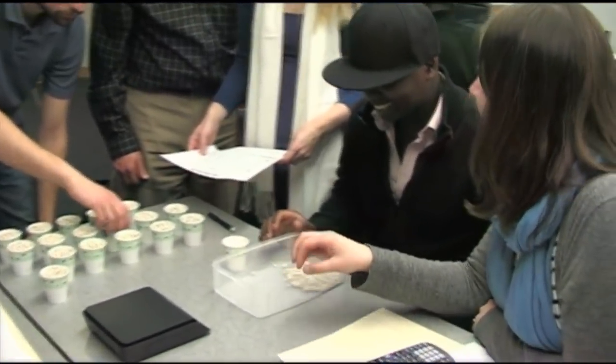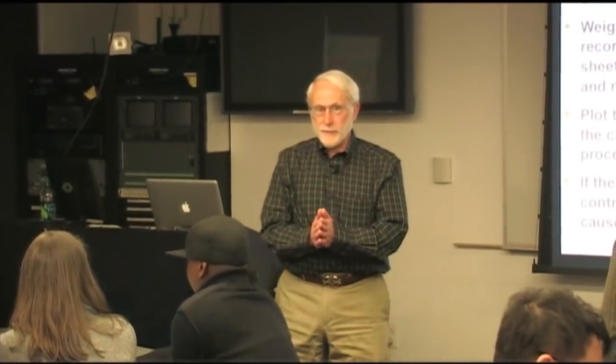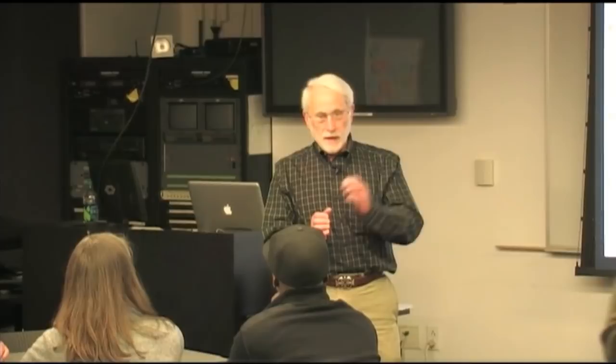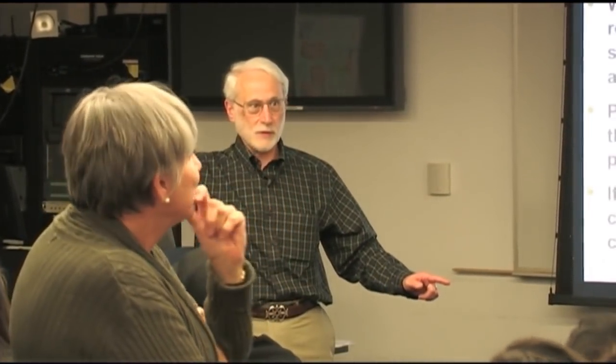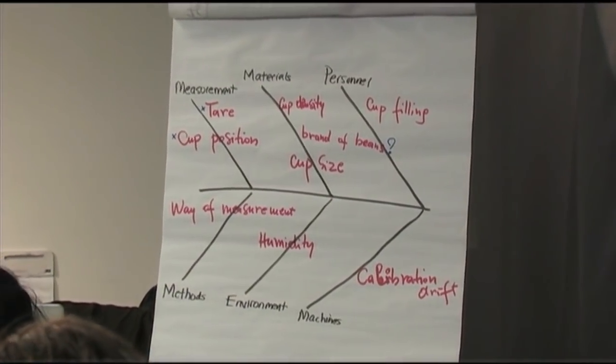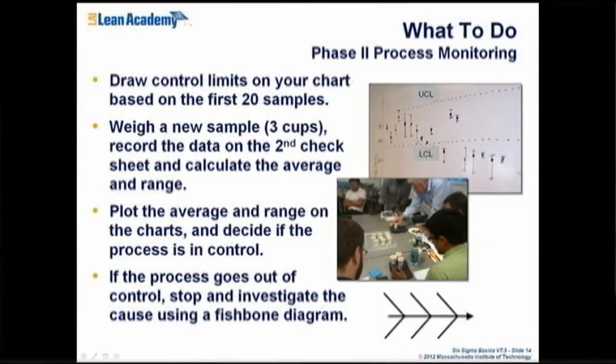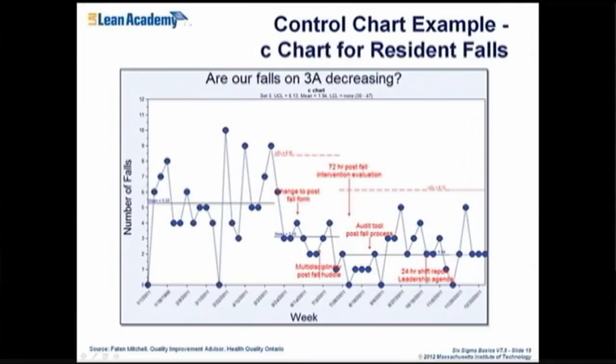Oh, look at that. Okay, so going around the room, we had a range of root cause analysis approaches, ranging from this table just saying, we think this is the cause, and they tested and that was the cause, so they just jumped right to a conclusion. We had a very structured process over here. But this is a way to make it visible. If you go into a facility that's under statistical process control, the employees are trained on this, and they're trained to recognize this kind of deviation, and then they do something about it.